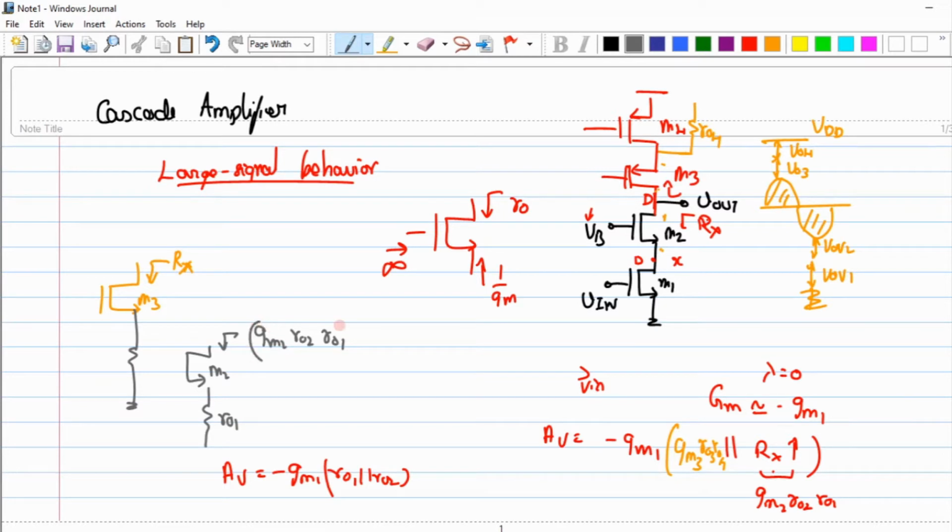This is the value I have plugged here. Now when I look through this M3, what happens to this resistance? It gets further magnified by the intrinsic gain of this M3. So it's as simple as that, and I can shoot up this Rout. Clear? But you always have to be cautioned that whenever I stack transistors higher and higher, what will I be losing? The output swing would be reduced. Okay, so be clear with that.